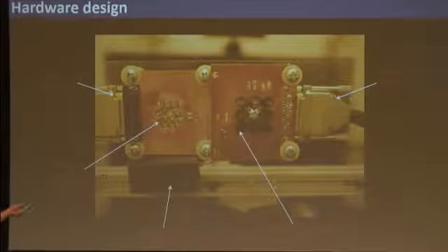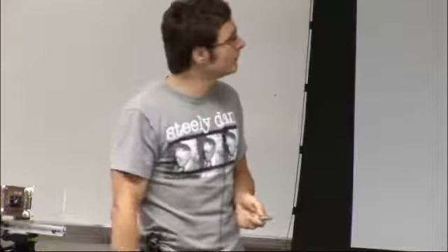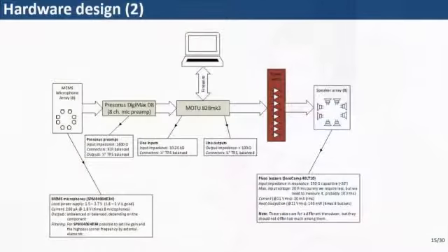We interface everything to a PC using, first, the Motu, using DB25 snakes and so on. This is the battery to power the microphones, and this thing uses a separate power supply because we need to drive it to maybe 10 volts RMS. So we can't use a battery for it. Okay, so this is the overall design of our system.